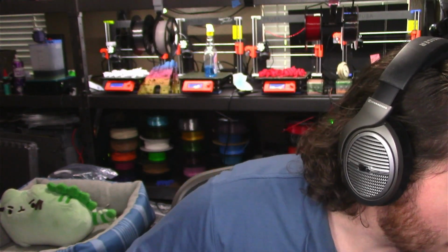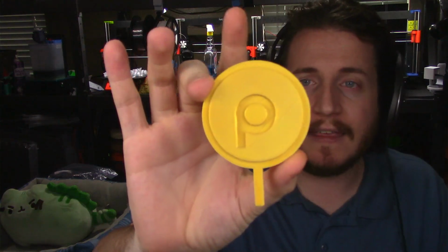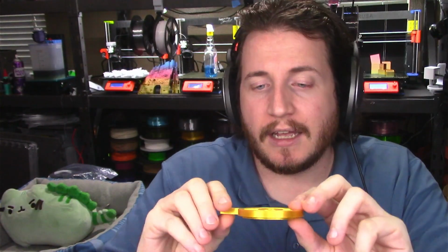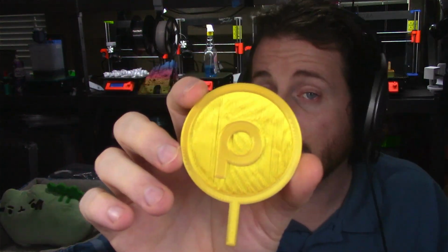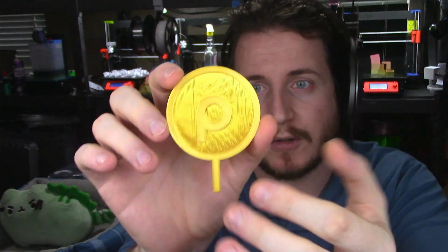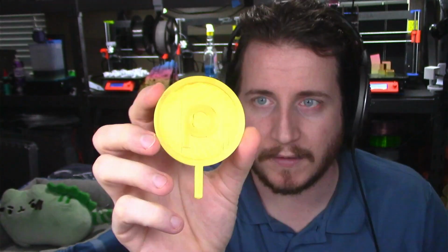It actually completely, in my experience, removes the smooth look and shininess. So this is from a previous project that we did. This is silk gold filament. If you notice, it's not all that shiny. And yet we turn it over to the other side where there wasn't ironing. This was the bottom layer, okay? There's another piece that goes over it to basically make the same thing on both sides.